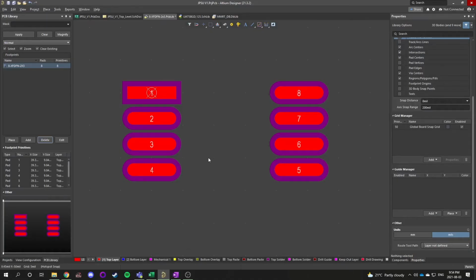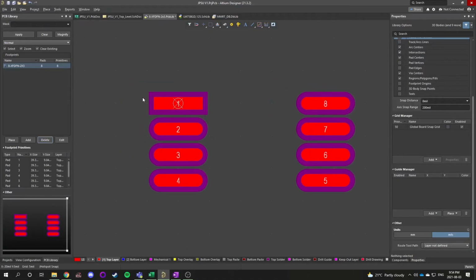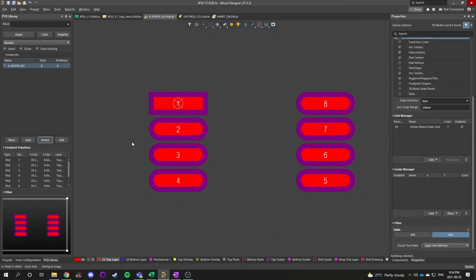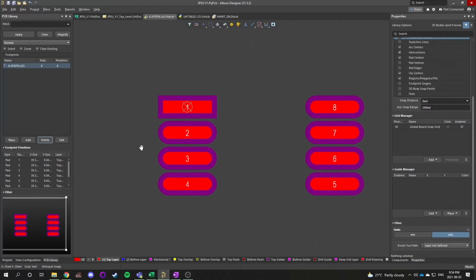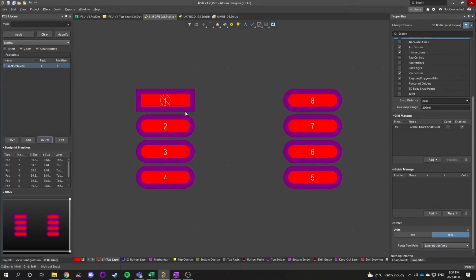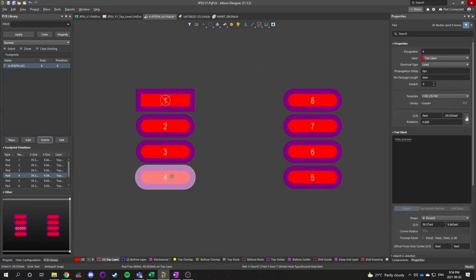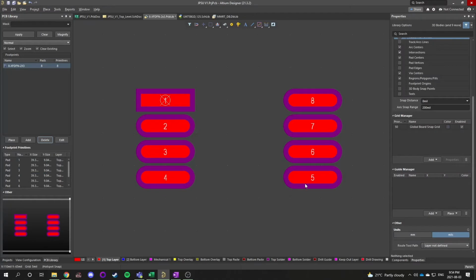So when we label a pin 1 marker, we always just place a little dot beside pin 1 of the chip, so we know which pin is pin 1 when we look at the board. And this will help us determine the numbering for all of the other pins. Since IC pin numberings always start in the top left, and we go down. So 1, 2, 3, 4. And then when we get to the other side, we count up. So 5, 6, 7, 8.